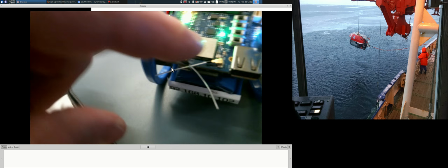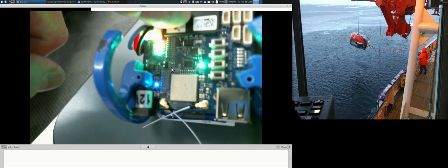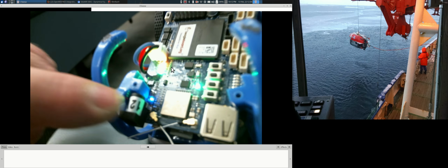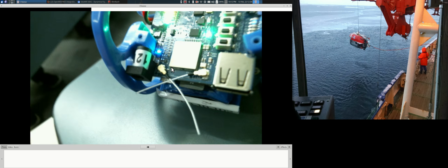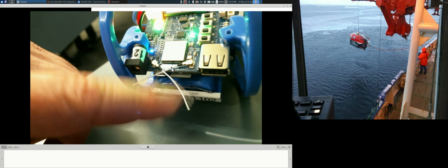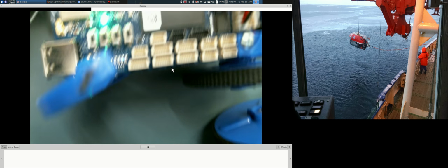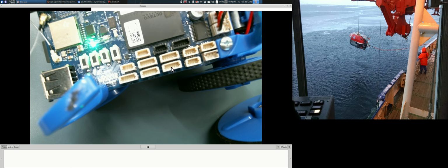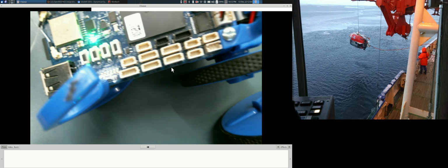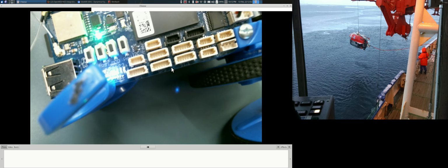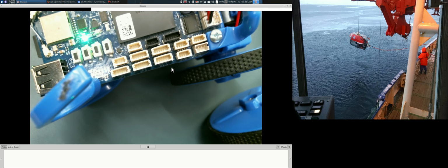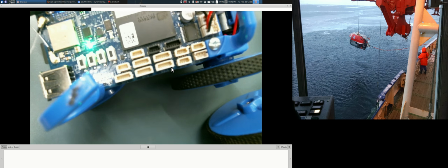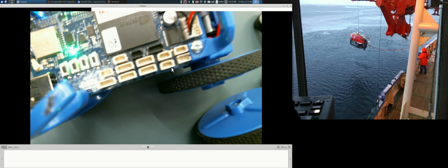And this is the CPU and memory here in a module. And this is the Wi-Fi and Bluetooth driver. The whiskers are the Wi-Fi antennas. And over here are a bunch of connectors that support serial input, serial output, analog output, SPI and I2C, which is a 1 or 2 wire serial interface for interfacing to external devices, so it's very I/O rich.